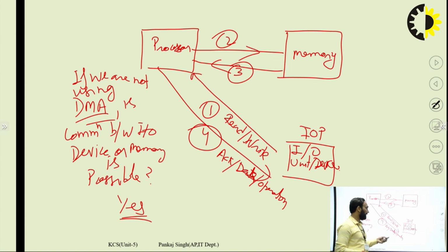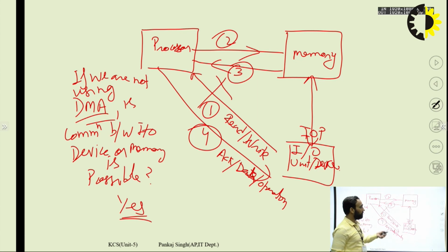If we see here technically, there are only 2 devices involved: memory and IO devices. If we connect memory and IO devices directly and exclude this link, we can save cycles to share the data. If we create a mechanism or any hardware that allows direct communication between memory and IO devices, we can increase the speed and throughput of a machine without additional hardware and software specification.